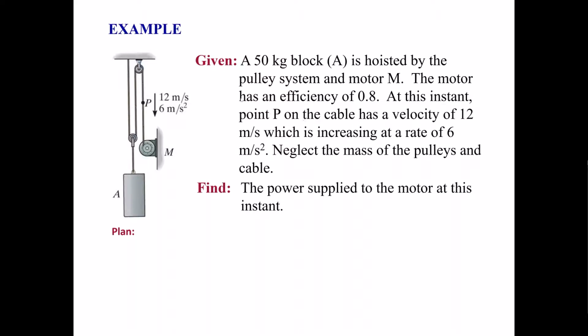So some of the things to think about here, if you're looking at how far this goes up, we have a pulley, so this is all the same cable. And we have essentially, for this to go down 1 meter, let's say, this would only go up half a meter. This block would only move up half, right? So we need to think about that in terms of the relationship between position. So the displacement of the block is related to the displacement of this point. Okay.